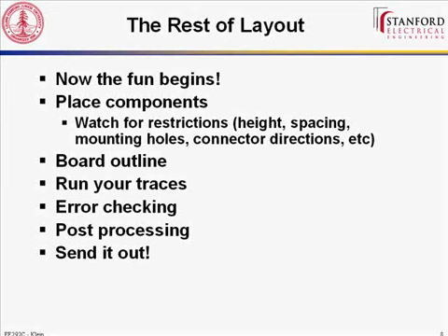factors. I mean, in a couple tens of megahertz, the shapes of your traces don't matter too much. When you get to 50 to 100 megahertz and you're dealing with memories, you start to care about the lengths of your traces. And when you get to hundreds of megahertz and higher, in gigahertz, you care about the shapes for reflections when you're actually having a 90 degree. But for everything you do in this class, you'll do right angle traces, so you don't have to worry about the shape too much.